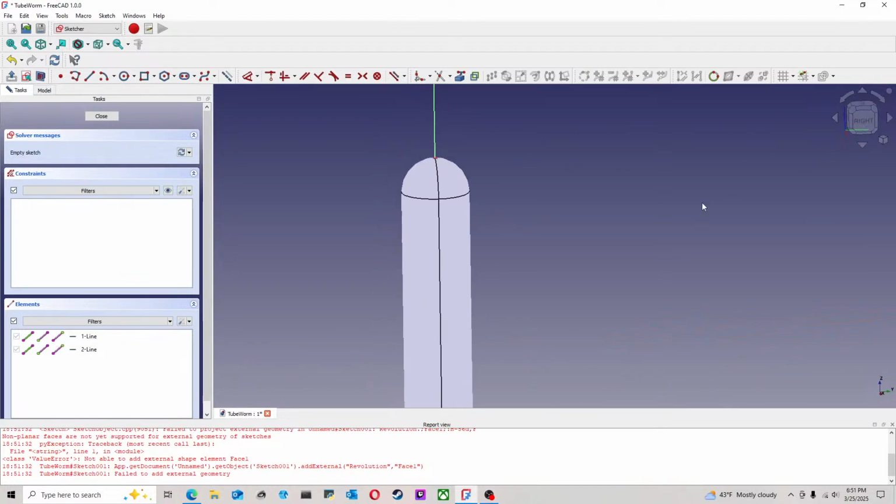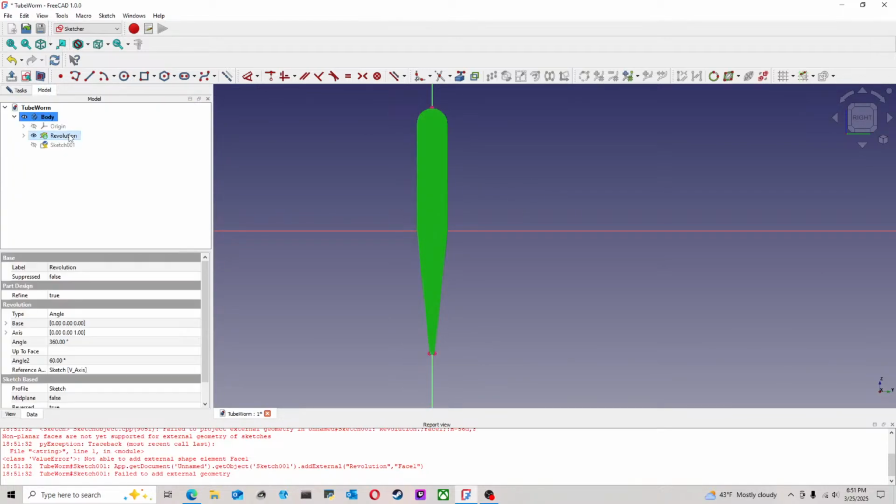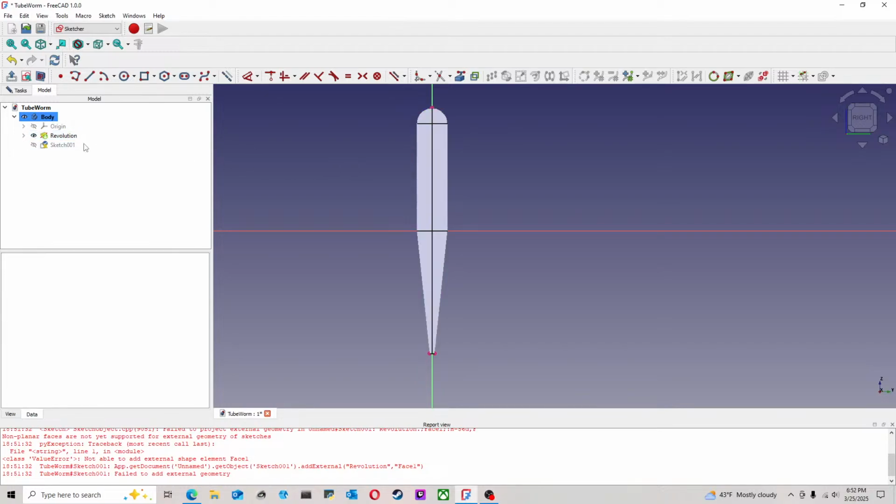and that's going to leave those points in my sketch that I'm creating. And I can actually come back here and hide my body so I can see the reference geometry I just created. All I have to do is select this in my feature tree and hit spacebar, and it's going to toggle that back and forth.